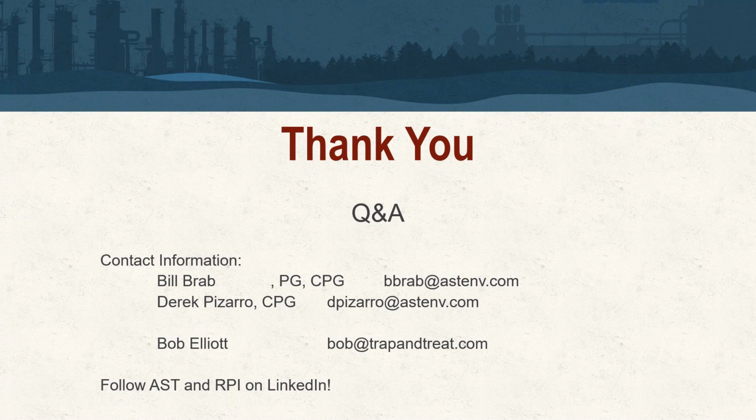Sure. And I think you touched on, there's actually a couple questions here about cross-contamination within that water column. So I think you handled that one as well. Is there anything you'd like to add to that? No, I think we're good. I think the surface casing prevents it from the overburden side, and then other tools can be utilized, like the liners or whatnot, if we're concerned about vertical contamination within the open borehole itself. Yep.